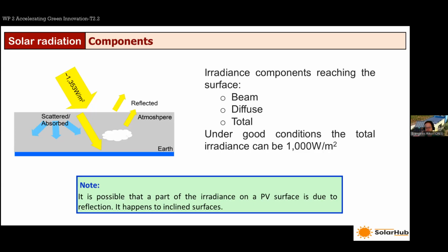We have both options here. However, you have to transform the data, or recalculate the measurement, in order to transform it into standard test conditions. Understandably, the reproduction of diffuse irradiation within a solar simulation is not very straightforward.